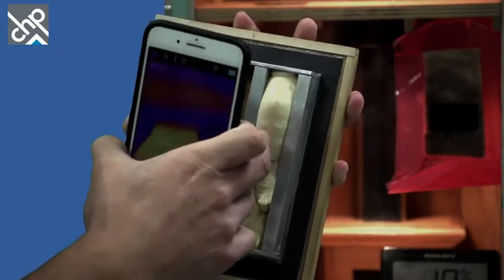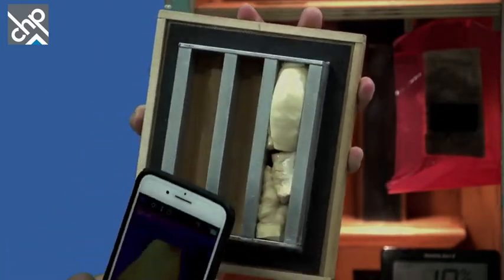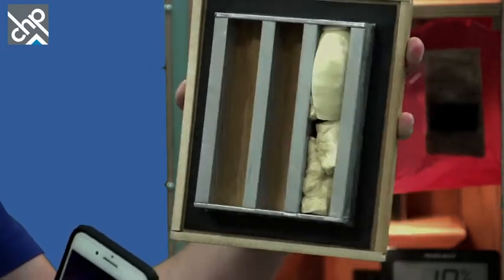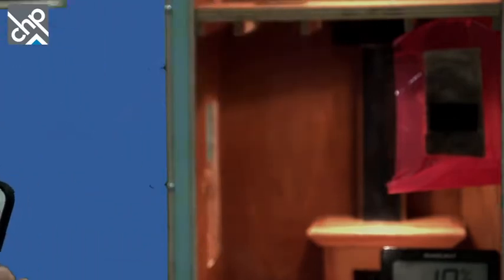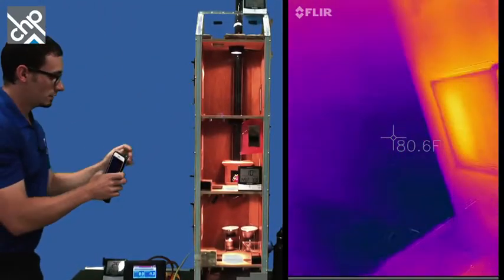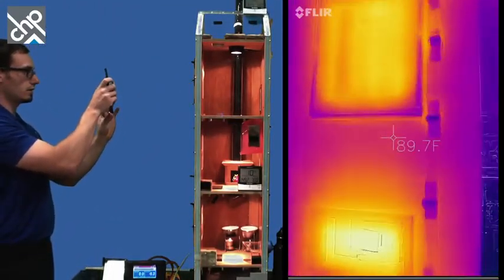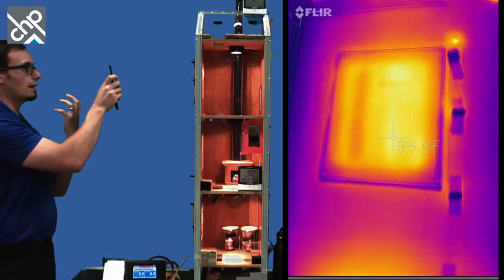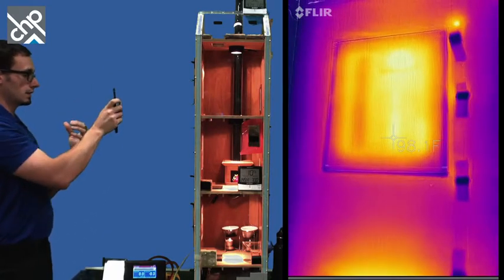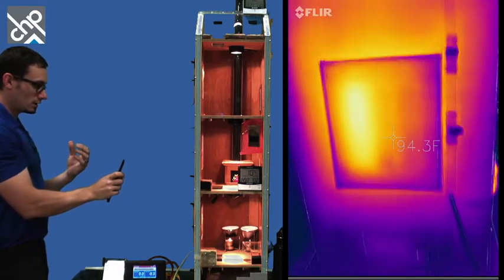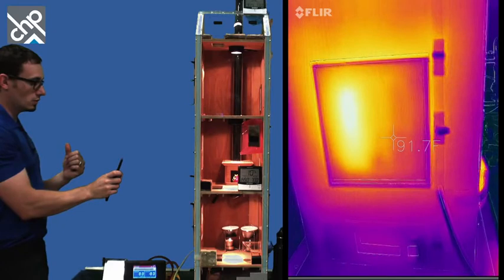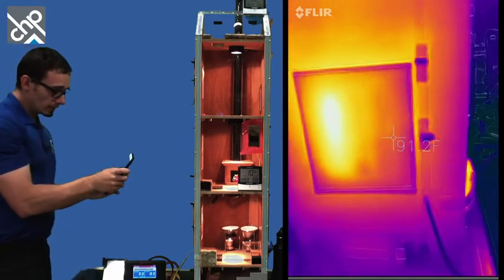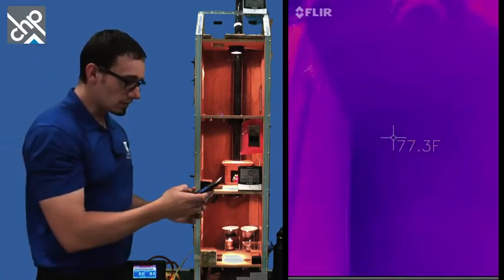So it's not showing up as much protection because it's not. And then we do have the one side insulated over here, which is actually insulated quite poorly. The spray foam is not in proper contact. So this wall compared to this wall, let me put these back up here, this one's got a lot more heat loss as compared to this one down here. You can actually see that in the surface temperatures as well. So that is conduction.